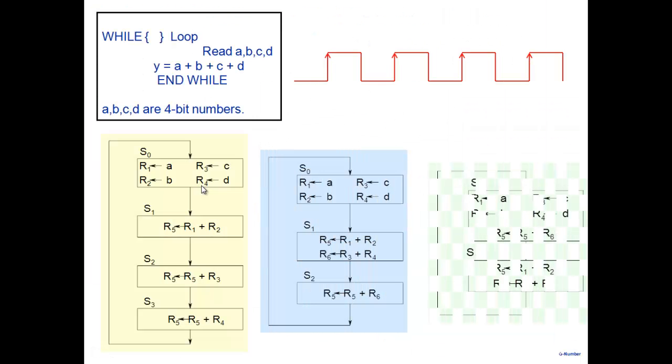So we have said that this is a finite state machine. We said it goes from one state to the next. This has a name called algorithmic state machine, ASM. Instead of the FSM that we had earlier, that FSM has evolved into an ASM, an algorithmic state machine. So we have an algorithm which we have broken down into how the algorithm is carried out in different states. What I'm saying is that I can take this description and get this particular ASM description in an intuitive manner by looking at it and deciding what to do.